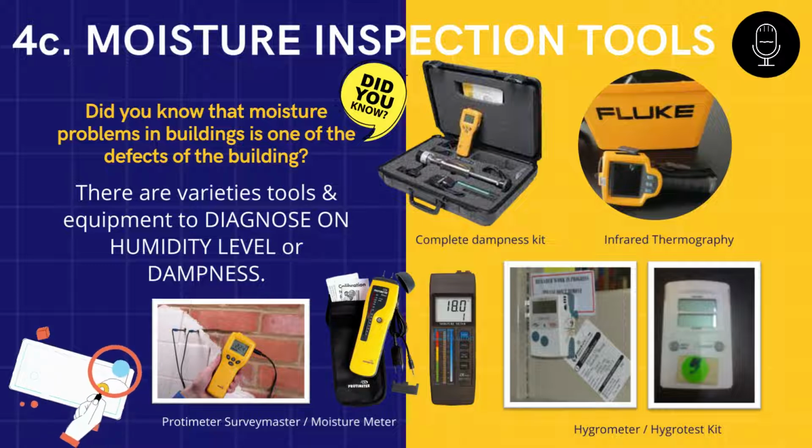Did you know that moisture problems in buildings are one of the defects of buildings? There are 5 tools that are usually used to diagnose humidity levels or dampness, as shown in this slide. The moisture level in concrete or wooden structures, for instance, can be investigated using a protimeter or moisture meter.